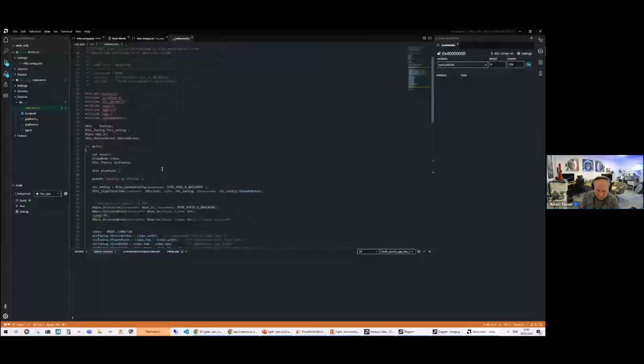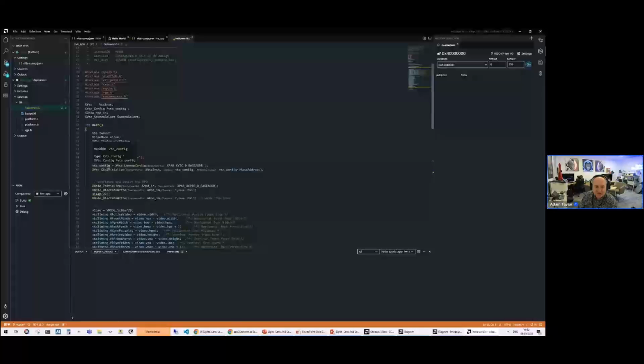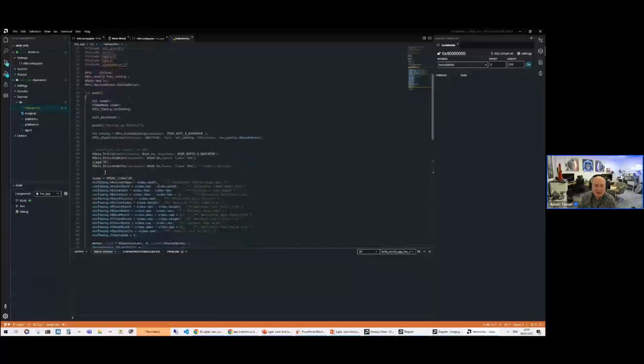All we've done is configure it to look up the configuration for the video timing controller. The video timing controller is what generates the output timing for the AXI stream in to video out, and we need to set that up. Even if we're using the timing from the input video, we need to tell it that it's using the timing from the input video, and that's done via the software. And we also need to set up the GPIO such that we can drive the GPIO hot plug detect when we're ready in our software.